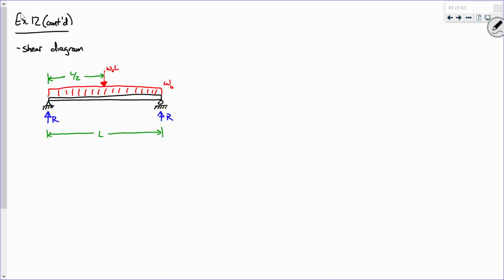All right. So let me ask you this: do I need to do the statics to solve for this reaction, or can you all tell me what the reactions are? WL over 2. Do you need me to, or? No. Okay. All right. So I'll say by symmetry, R is WL over 2. Okay. So let's go back to some more basics with structural analysis. So we've got this. Oh, come on, eraser. There we go. All right. So now it's time to